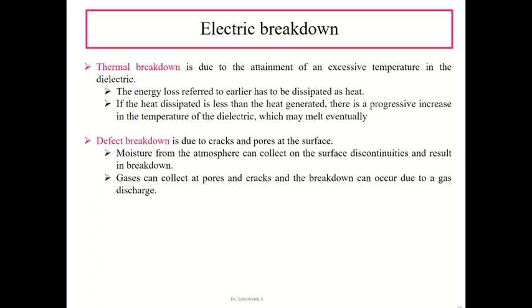Thermal breakdown is due to the attainment of an excessive temperature in the dielectric. The energy loss referred to earlier has to be dissipated as heat, and if the heat dissipated is less than the heat generated, there is a progressive increase in the temperature of the dielectric, which may melt eventually.